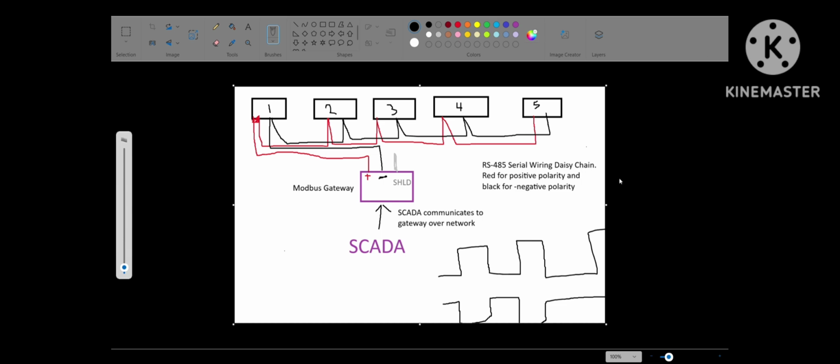All right, so anytime you're going to troubleshoot a problem, after you make your problem statement, knowing what you're looking for, then you need to develop some kind of functional diagram or block diagram showing how the communication works. In this case, I'm trying to solve a communication problem. So there's a couple things I need to know. I need to know how my SCADA platform, because that's where I'm seeing the alarm, is talking to these UPSs in the field.